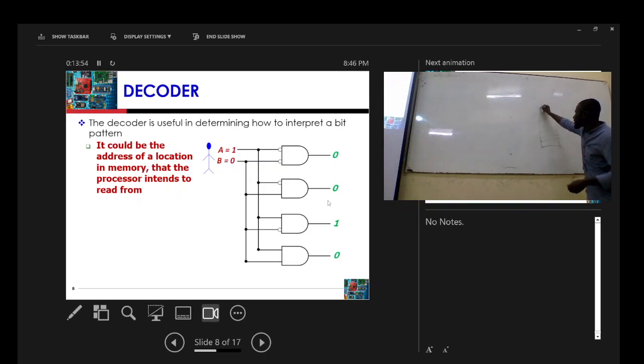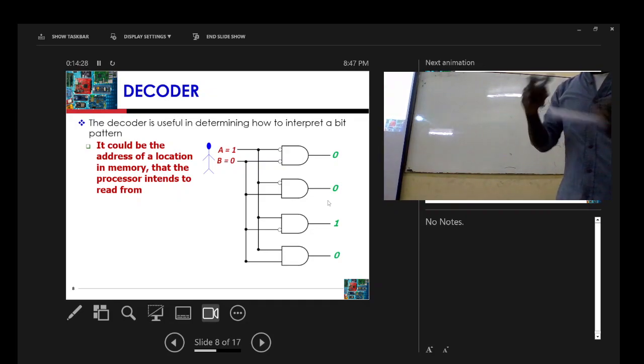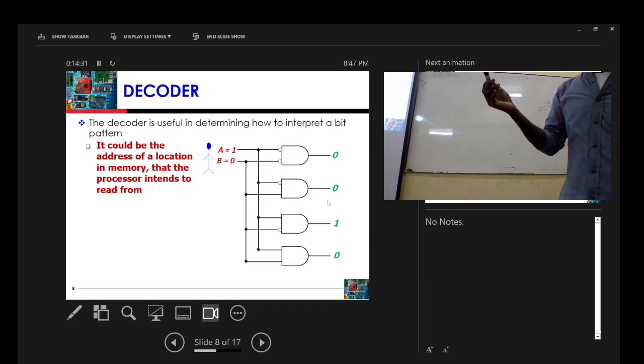And then you have what is known as the width of the memory, and then you have what is known as the depth. This is how the memory looks like, and then each memory location stores a value. This is how the memory model looks like based on the width. So if my width is 8 bits, this can store 8 bits, 8 bits, 8 bits, 8 bits, right? And then the depth will now determine how many of those locations are there. As easy as that, right?